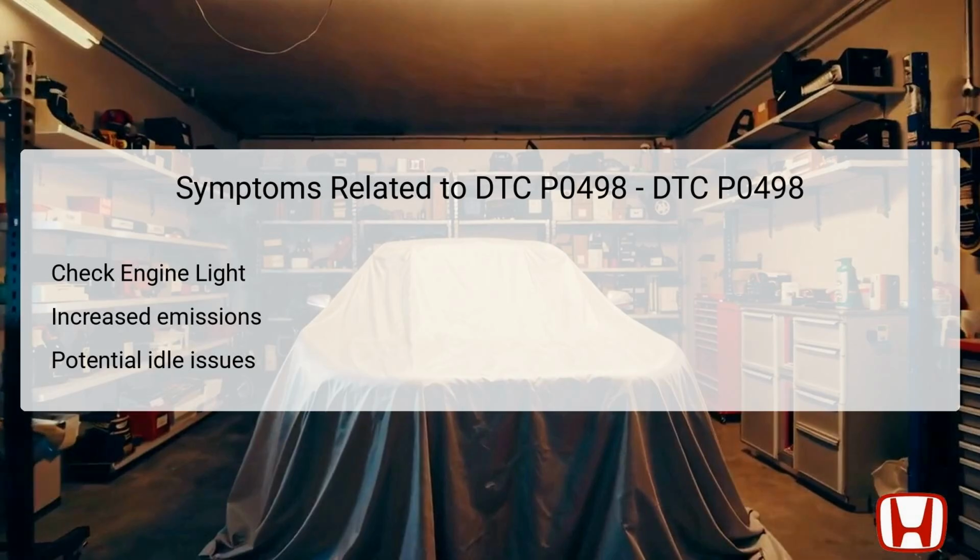Additionally, if the vent shut valve is not functioning as intended, it may lead to increased emissions, potentially causing the vehicle to fail emissions testing. There might also be idle issues, such as surging or unstable engine performance, attributed to improper vapor management. Observing these symptoms can guide technicians towards resolving the underlying issue, signified by the DTC.